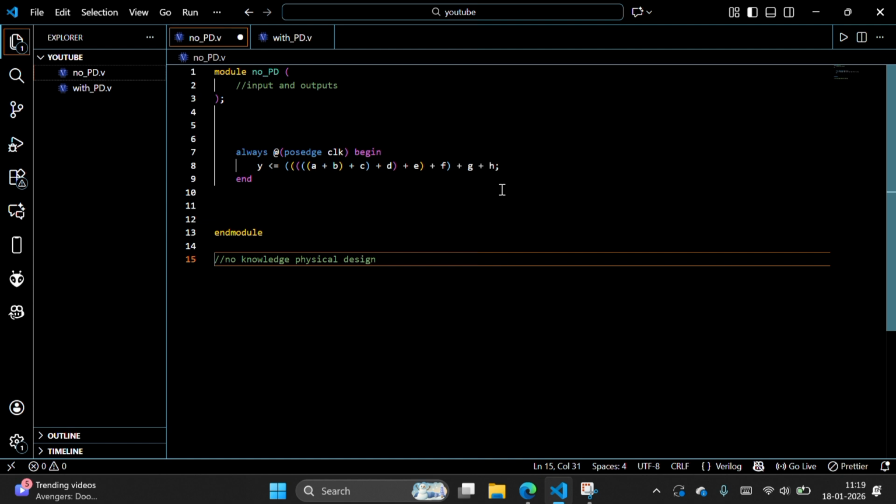So what's wrong with it? The logic is completely correct, but you know what happens if you synthesize it? This block of code will be generated as a giant combinational chain of blocks. Once you synthesize this, for a single cycle there will be a huge combinational block executing all this in a single cycle, putting more adders into one design. So it will be chaos. I cannot even imagine that. That level of destruction will be happening at the synthesis level.